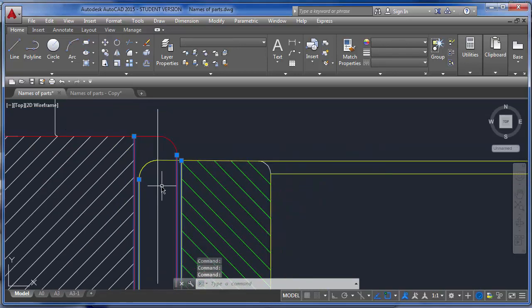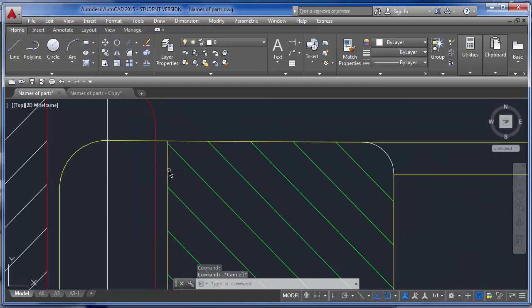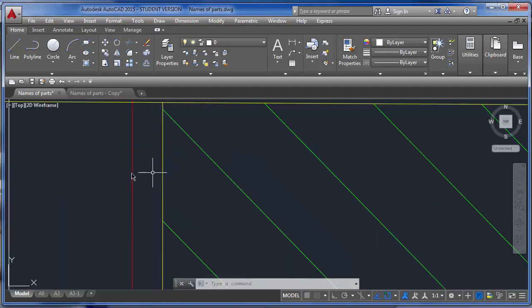So if your gear goes inside this or crosses this bottom clearance, it's going to get stuck. How far this distance should be, there is a special calculation for that. You learn it in machine principles, but for an easy calculation we just divide the module by 4. Whatever your module is, you divide by 4 and we get this distance here.